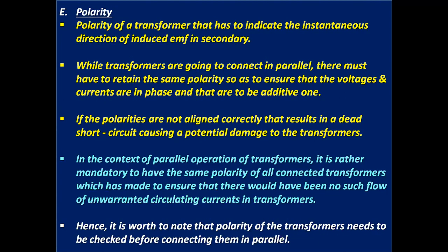E. Polarity. Polarity of a transformer indicates the instantaneous direction of induced EMF in the secondary. While transformers are connected in parallel, they must retain the same polarity so as to ensure that the voltages and currents are in phase and additive.